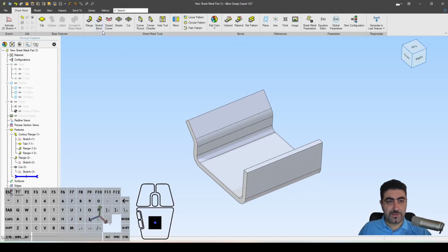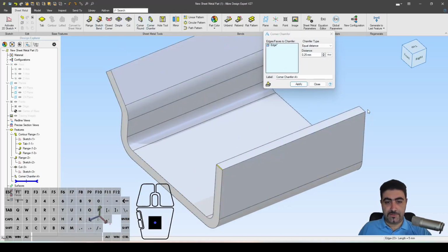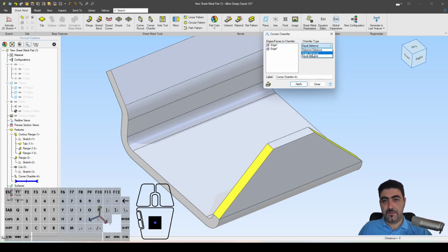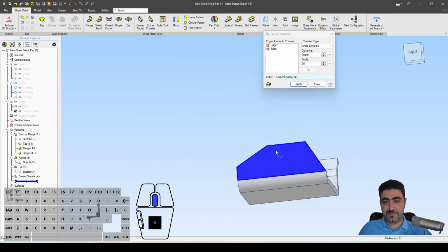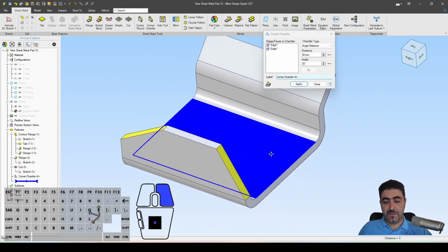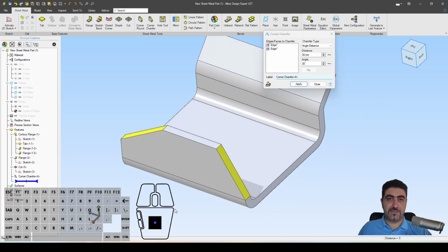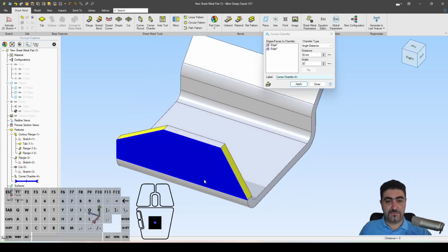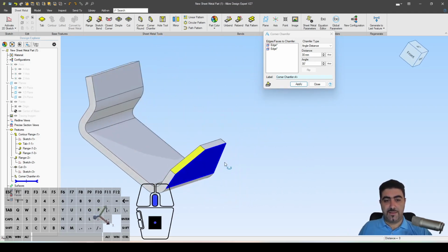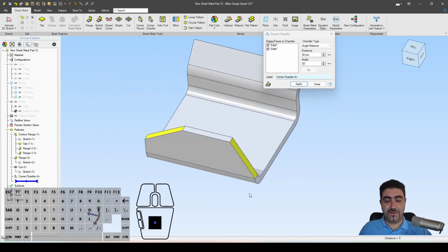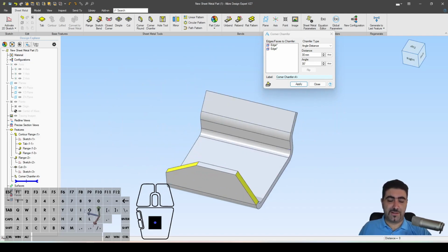And I will show you a little tip here. So if you select both of these and create an angle distance chamfer type, right? I'll make this 30 degrees. We update the preview and it is wrong. And you will see this happen in most CAD systems. I know for a fact Fusion does it. I think SolidWorks does it as well, and so on. That's a good reason to create the part in half and then mirror it like TooTallToby did.